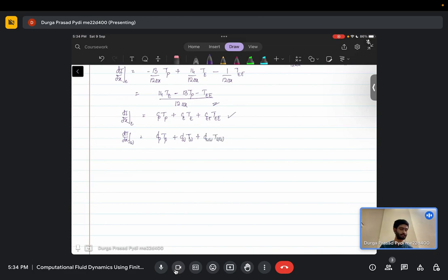So what this essentially means is, now you will have your equations in a slightly different form. If your cells are numbered in this way, this is my cell centroids, this is my kth cell, this is my east cell k plus 1, k plus 2 is my east east cell, this is my west cell.